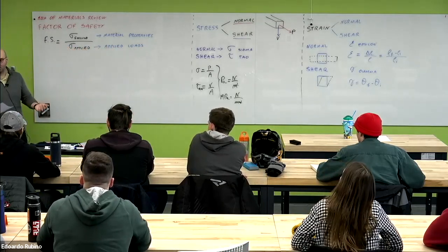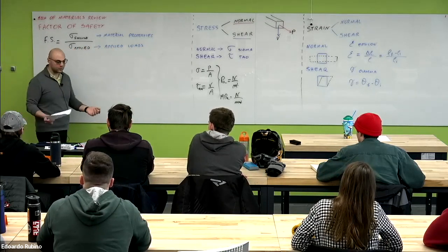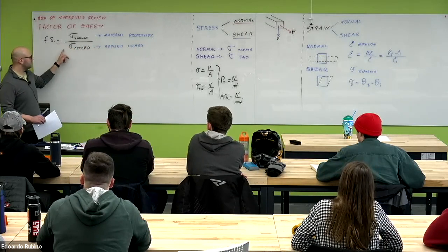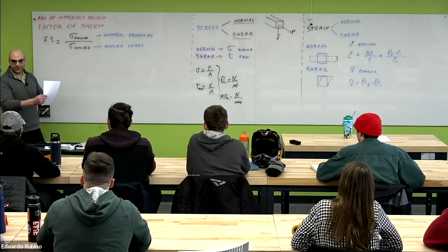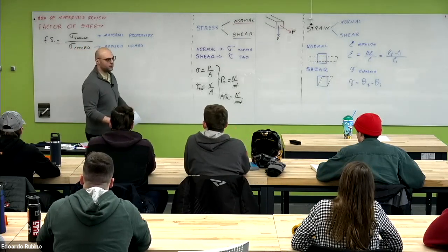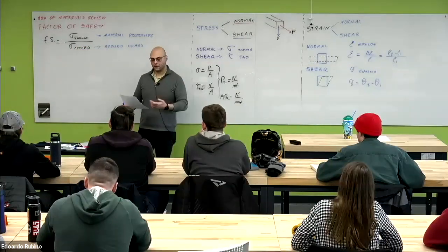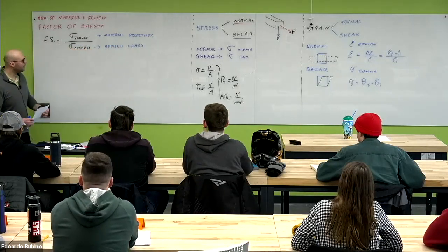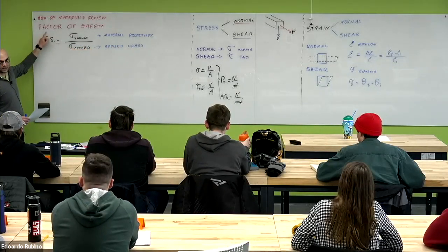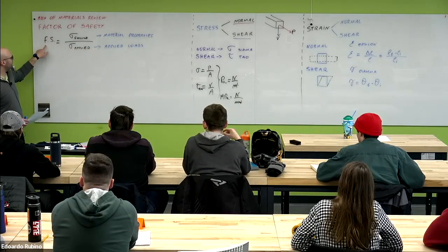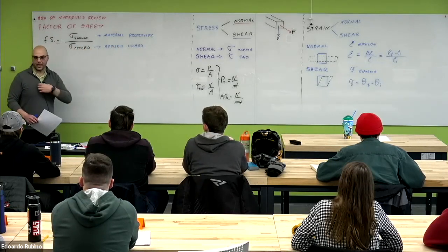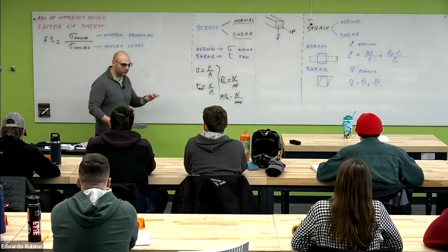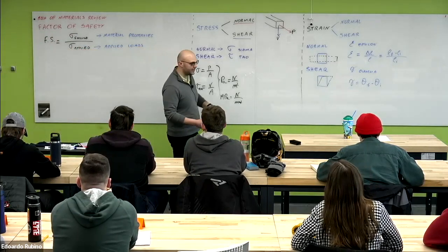So we can have different types of loads at the same time, which means we have to work on this sigma applied through several steps, which include Mohr's circle and combined loads first, and so on. But the physical concept of the factor of safety is always the same. It tells us how far we are from having failure for that specific material and that specific structure.